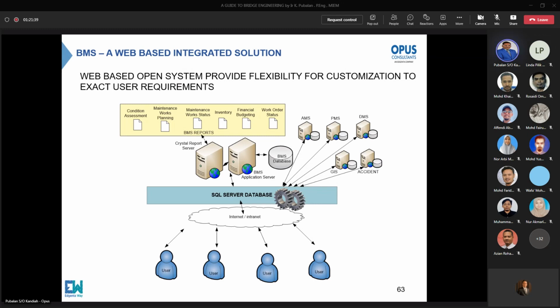The way I look at it, the Bailey bridges, like what I said, the primary function is that it can be dismantled. So if they use checkered plates, then the number of joints will be less, so you have larger members to dismantle. You may have a checker plate area of about 3 to 4 meters length and 3 to 4 meters wide, so then you need to remove it. That is probably why they found that using timber members is easier to remove, and also, you know, there is some flexibility in the timber.